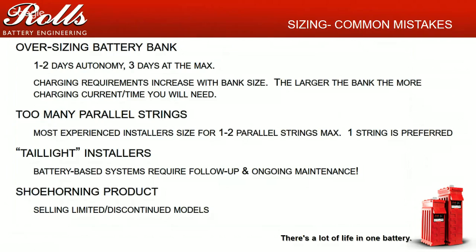Shoehorning product. This is pretty common, especially in Africa and Latin America, where lead times can be an additional 4 to 6 weeks due to ocean transit. It's where you've got 60 L16s in stock and no 2-volt cells, so you just throw in 4 or 5 parallel strings of batteries and call it good. You want to make sure you plan for that installation and have those.